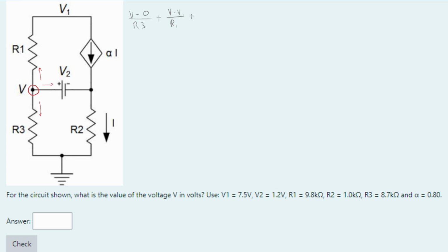So inside of here, what we have is the voltage across this part. Now we can see that the voltage right here is facing this way, right? So that means the voltage at this node right here, and we'll call this V3, is just going to be equal to our voltage minus our V2.